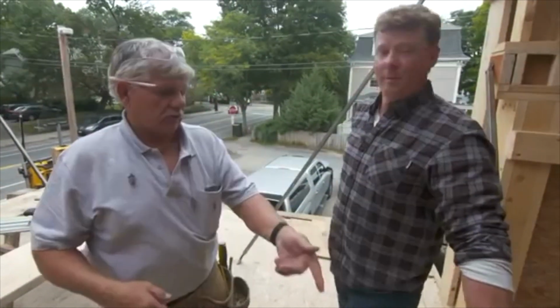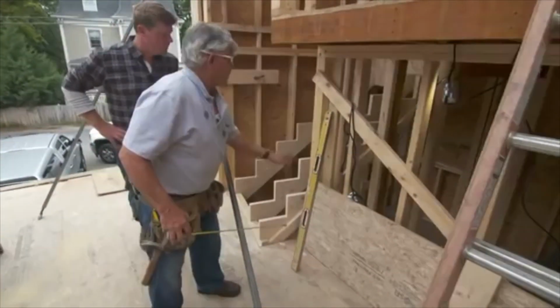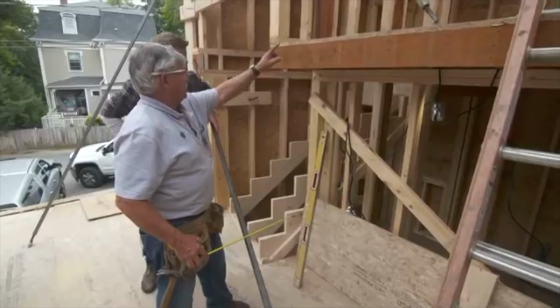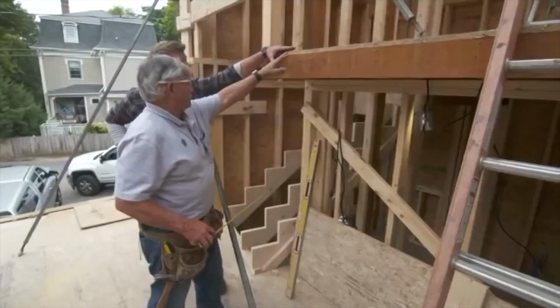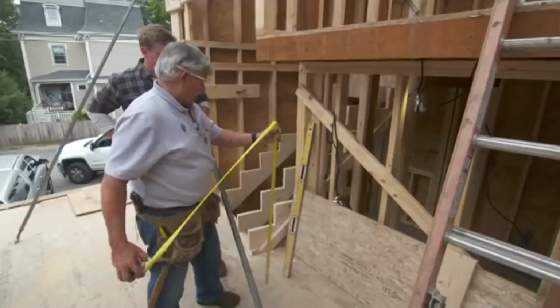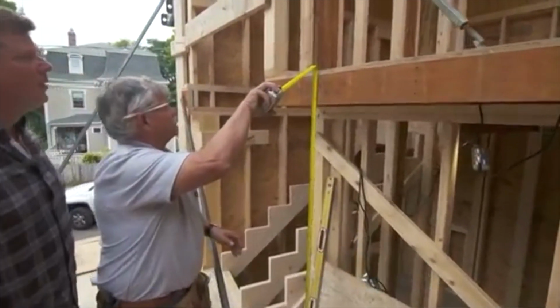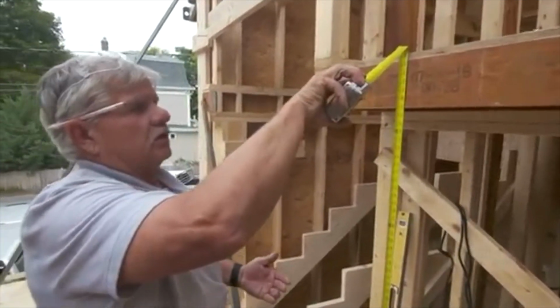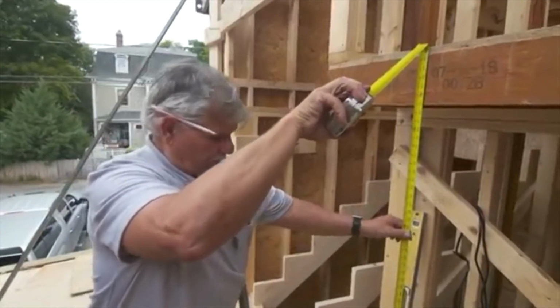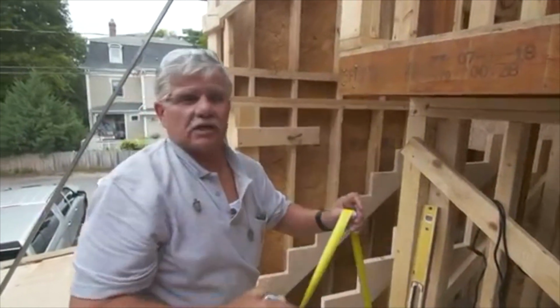So let's take a situation like this right here. If I'm going to measure from this floor to that floor, I know that the finished floor, whatever's going to go on that floor, is going to go on this floor. So the thickness is exactly the same. So now I can actually take my measurement and I can go from rough to rough. 69 1/4. And now if I put finished floor on the bottom, it'll be 69 1/4. Okay, so I've just added that in.